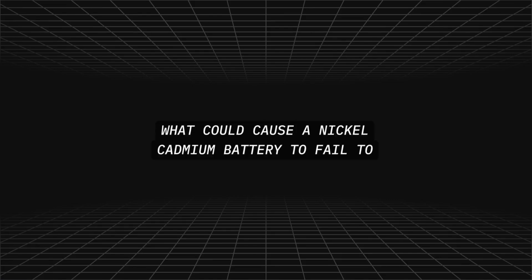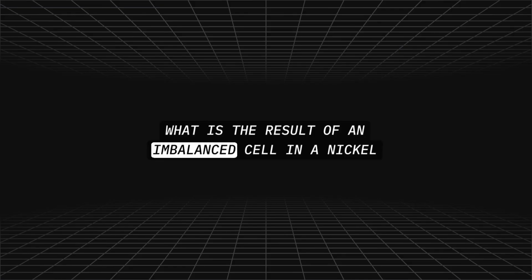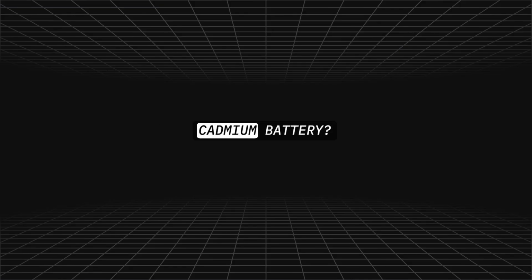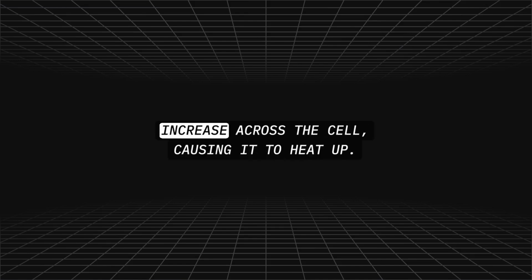What could cause a nickel-cadmium battery to fail to deliver its rated capacity? Cell imbalance or faulty cells. What is the result of an imbalanced cell in a nickel-cadmium battery? When a cell has a low internal resistance, the current will increase across the cell, causing it to heat up.